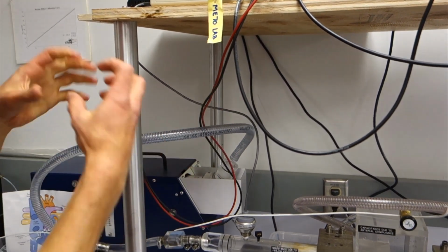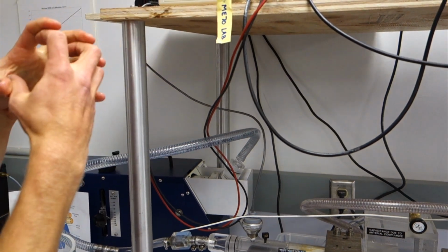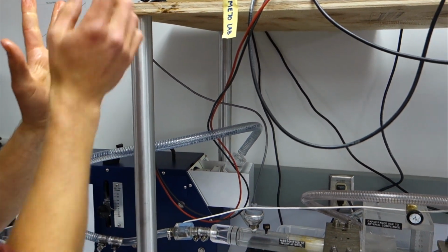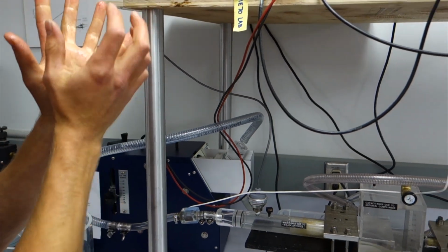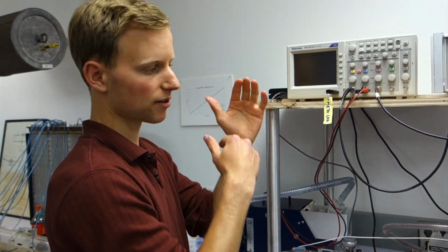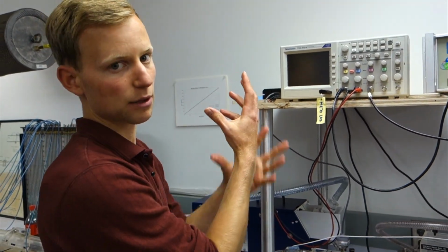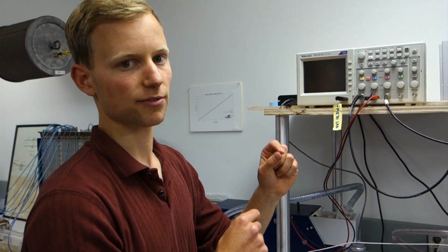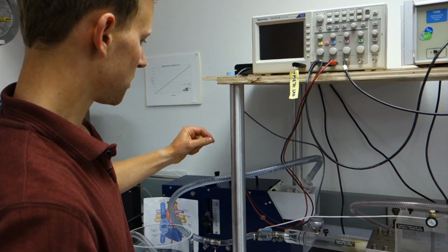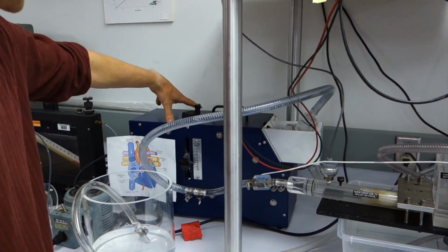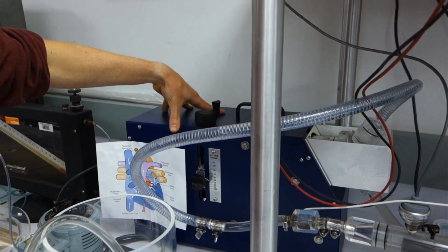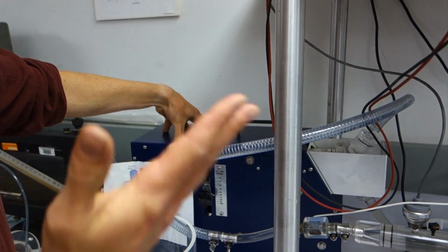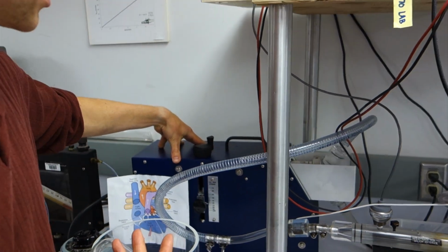This valve here is a ball and socket valve, where there's a ball that just rests into a cavity, and when there is a high pressure above the ball, it gets pushed in and seals the joint. When there's a negative pressure gradient above it, it gets pulled up and it allows for flow through it. And it requires a very minimal pressure drop across it for flow to occur. So the pump is meant for simulating the heart. It has the correct waveform shape of a flow rate, which we're going to look at in a second.